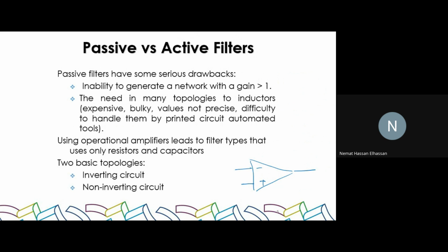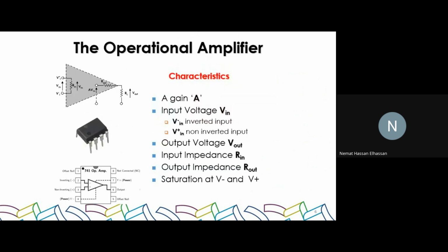Are you familiar with the transistor? The op amp is a circuit built with transistors. Okay? I don't want you to go into depth into the physical structure of it and how it's built and so on, but I want you to think of its circuit equivalent. In terms of a circuit, what does it look like? It looks like this. It's a component that has three effective terminals: two inputs, one output. So this is different than the resistor, capacitor, inductor. All of them are two terminal devices. The op amp is a three terminal device. It has two input points and one output point.